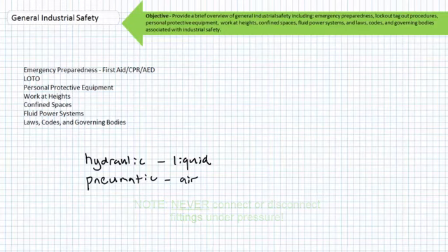Additionally, realize components such as accumulators or springs can store energy in a hydraulic system and also need to be released and locked out prior to performing maintenance. An accumulator is a tank, quite like a spring that pushes on the fluid. The pump may be turned off, but lifted or suspended objects and components like springs and accumulators may still pressurize the system. Fluid under pressure and moving through a system can sometimes present thermal dangers.